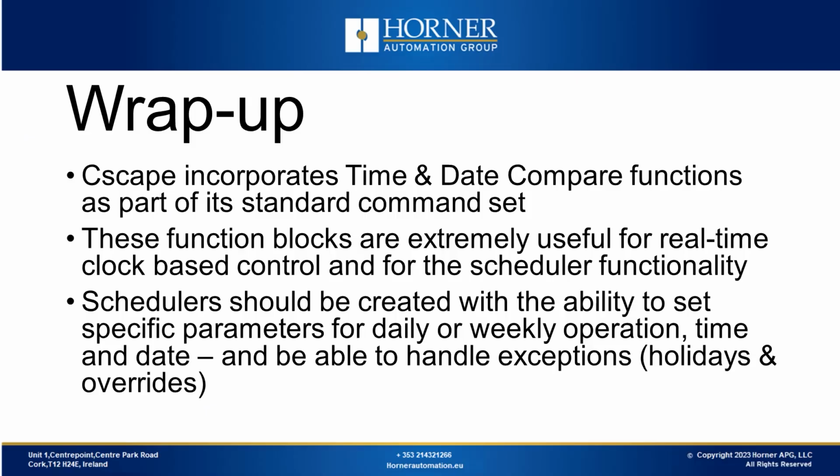Cscape incorporates built-in time and date compare functions, eliminating the need for custom function blocks. These functions are valuable for real-time clock-based control and scheduler implementation. A scheduler should be capable of managing time and date parameters, allowing for daily or weekly operations. It should also handle exceptions, such as holidays, and potentially accommodate manual overrides. While manual overrides may fall outside the scheduler's scope, they should still be addressed in the overall system.